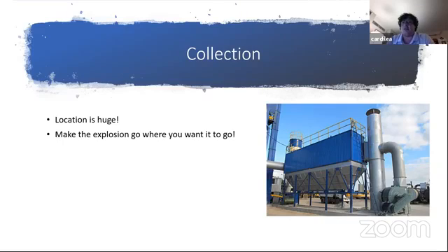And kind of adding on to that point, one of the ways that some areas prevent a dust explosion from happening is they do put moisture into the environment to prevent the explosive atmosphere from taking effect. Because if you have a lot of humidity, again, less likely to have an explosion. So that's a very good question. But yeah, collectors are basically the first line of defense. Keep things clean and put it into a collector, put the dust where you want it to go. And again, obviously, you don't want to be under an enclosure where there's no protection.